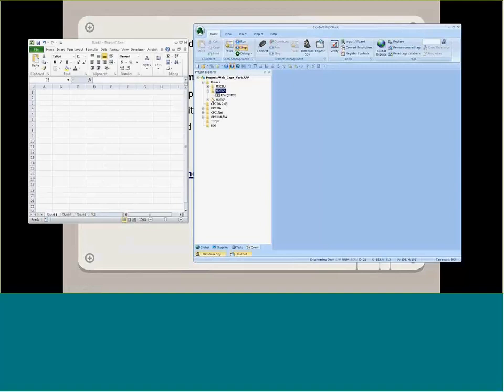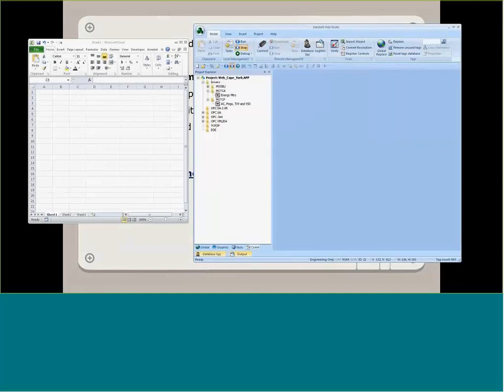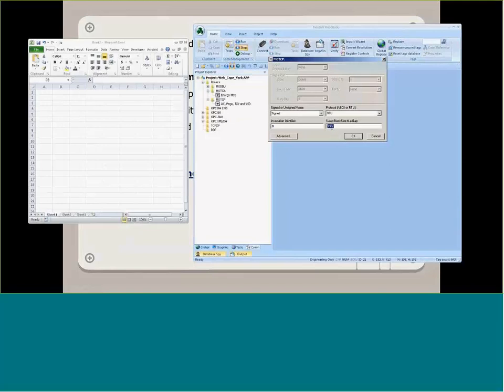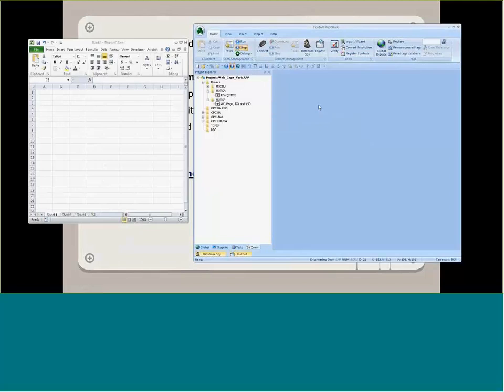What we did was the energy meters on this particular site could only handle a small max block size. So to prevent having to slow down the communications bus for everything, we actually used a different block, and we could get a few more blocks in. When you've got a lot of serial data, sometimes I think that's a good thing. We could also have individual timeouts and retries. So we thought that worked well.